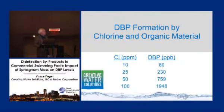So we heavily overloaded the system with chlorine, but you can see as the chlorine concentration goes up, the disinfection byproduct production goes up as well, indicating that there's plenty of organic matter in those systems, because you keep adding chlorine, you keep getting disinfection byproducts.